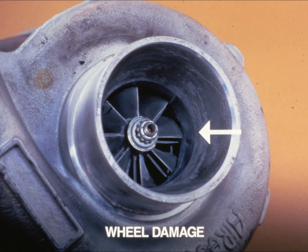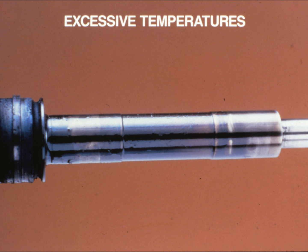Both lack of lubrication and contaminated lubrication failures initially show up as wheel rub problems. Excessive exhaust temperatures can discolor and damage the shaft and bearings, resulting in wheel rub. Oil passages can become plugged by coking oil under excessive exhaust temperature conditions.